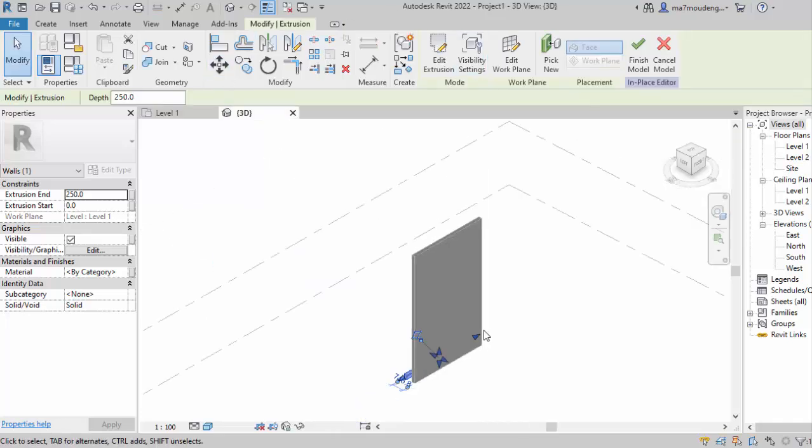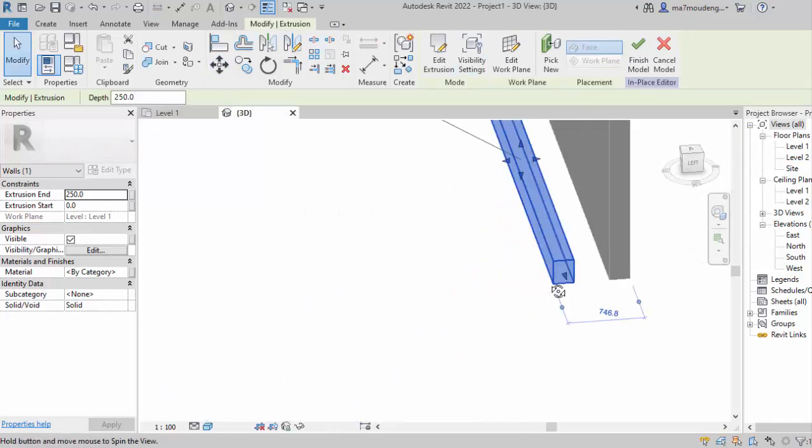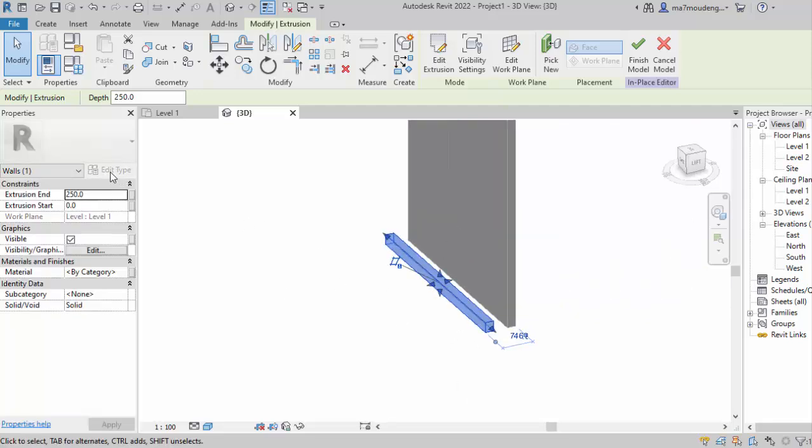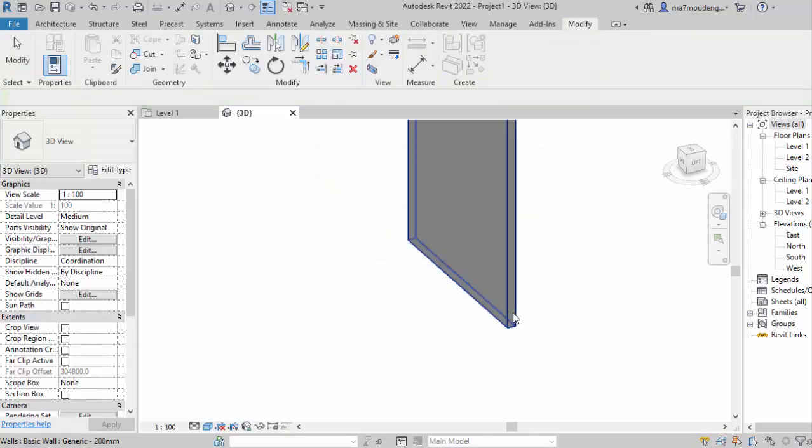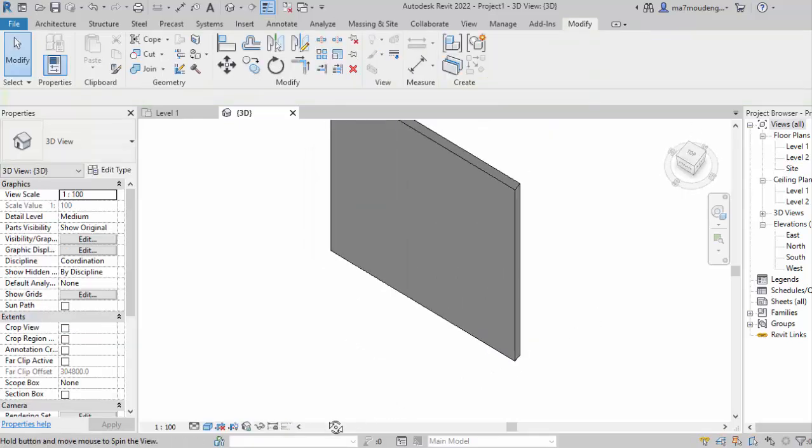So as you can see here, this is my extrusion that I've created. I can edit this parameter according to the height that I want. So this is what extrusion means. You give two dimensions, which is x and y, or x and z, whatever, but the last one will be decided by a different parameter.